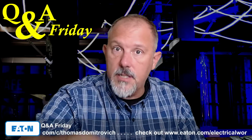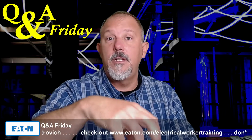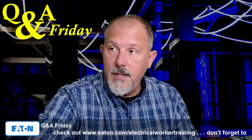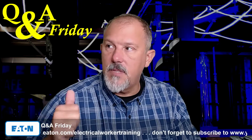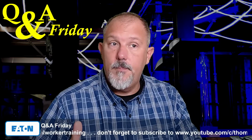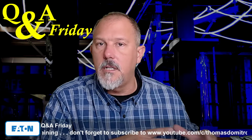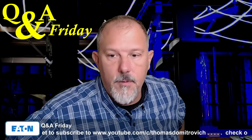So those are my three for calculations, understanding the per unit system, and doing a short circuit calculation using the per unit method: the Buff Book, the Red Book, and the Industrial Power Systems Handbook from Beeman is another good one. But pretty much everything you need to know, in my opinion, is in the Buff and Red Book. Those are my two that I would reference.